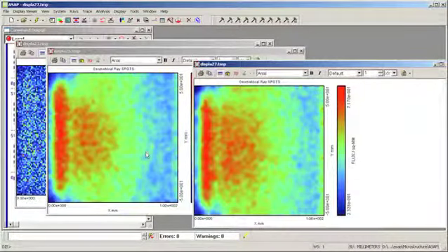Again, we compare the results of the explicit model with the unit cell model, and we see that the answers are very similar, demonstrating that the unit cell model is an accurate way to model microstructure in optical systems. The difference is not only in terms of ease of setup, but also speed of execution. The explicit model in this example took 45 CPU minutes. The unit cell model took less than 4 minutes.